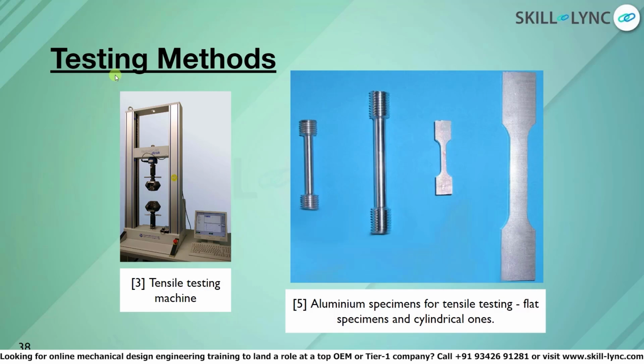However, different analysts have different ways of doing this type of test. Usually, the dog bone test is carried out only when there is availability, and in most cases the labs that perform these tests do them using rectangular shaped simple specimens. Other than that, we can also find cylinder shaped specimens, for which the grips are different compared to the ones for rectangular ones. Material samples are tested in a variety of geometries. However, with availability, the most common one is the dog bone structure.